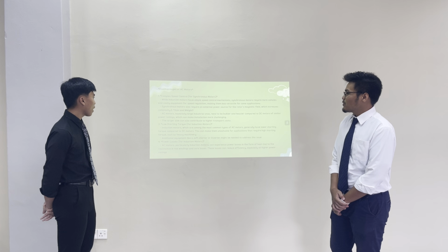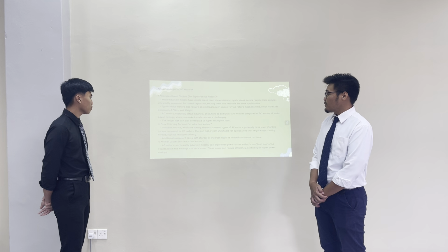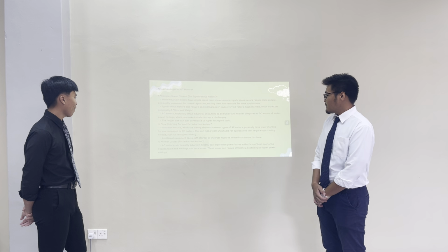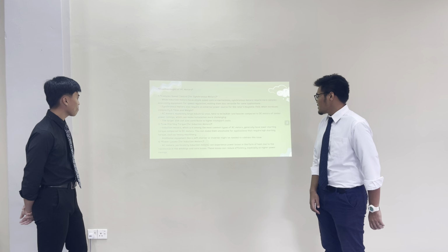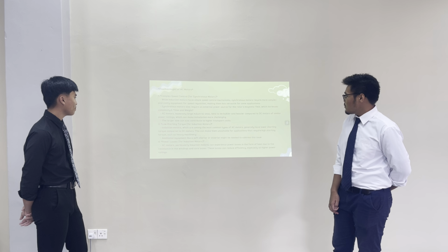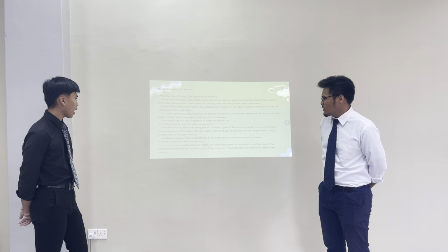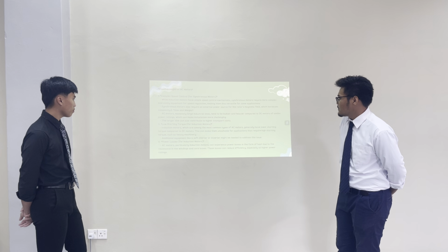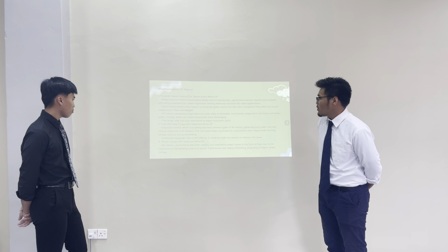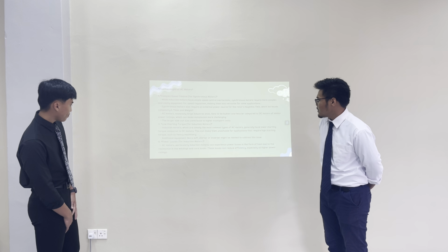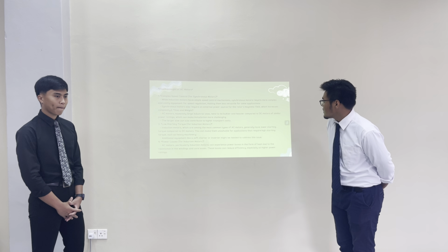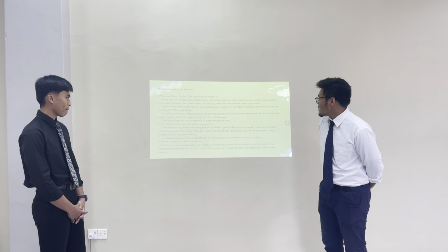Disadvantages of AC motors. First, complex speed control for synchronous motors. While induction motors have a simple speed control mechanism, synchronous motors require more complex and costly equipment for speed regulation, making them less versatile for some applications. Synchronous motors also require an external power source for the rotor's magnetic field, which increases complexity, size and weight.